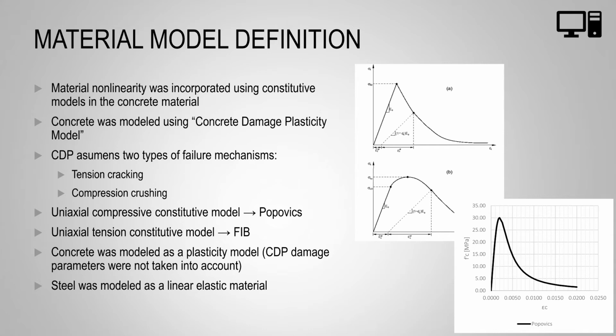And finally, when it comes to the concrete damage plasticity model, the direction of the cracks can be inferred as parallel to the direction of the principal strain in the places where the plastic strain is greater than 0. ABAQUS recommends using the equivalent plastic strains to see the crack directions.